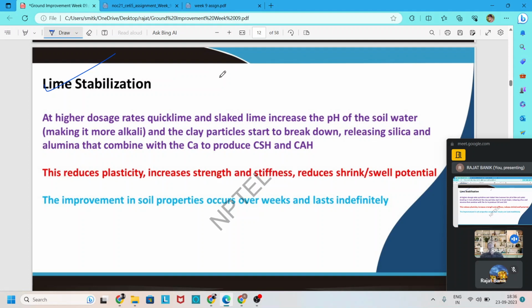That means in 10 days it is increased to 20 kPa. And this reaction is a continuous process, so over a period of time this strength is further increased. In this way, lime stabilization is suitable and beneficial for longer projects, for longer-term strength gain.